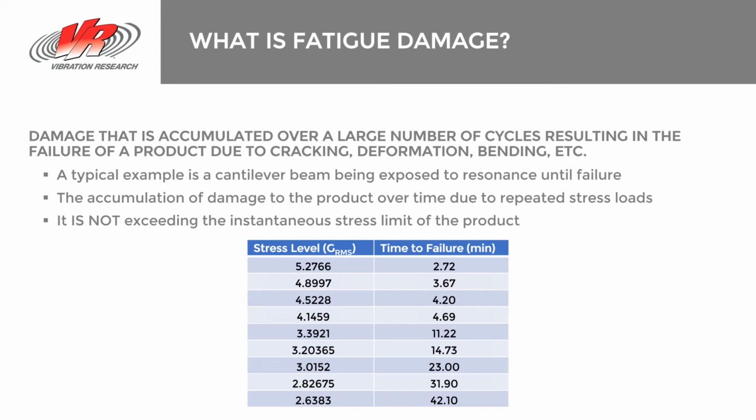The easy example is a cantilever beam that I might have mounted on the shaker. If I find the resonance of that cantilever beam and run for a period of time, how long does it take for that beam to fail, to actually develop a crack, or simply not have the mechanical characteristics that it had at the start of the test?